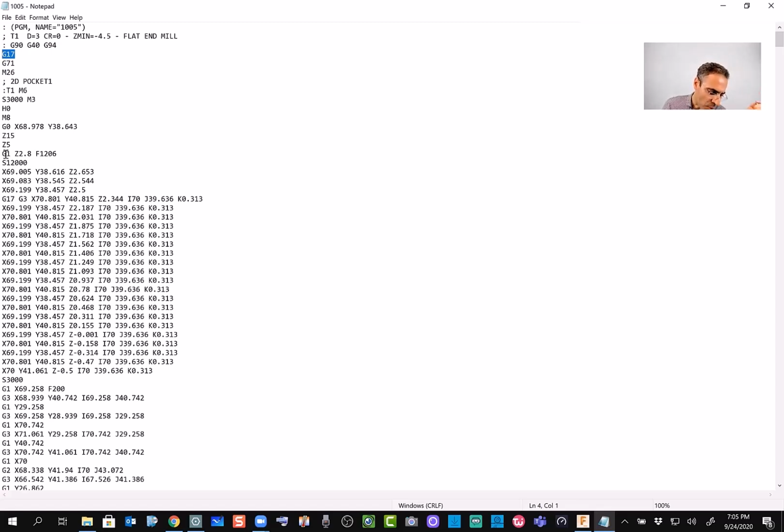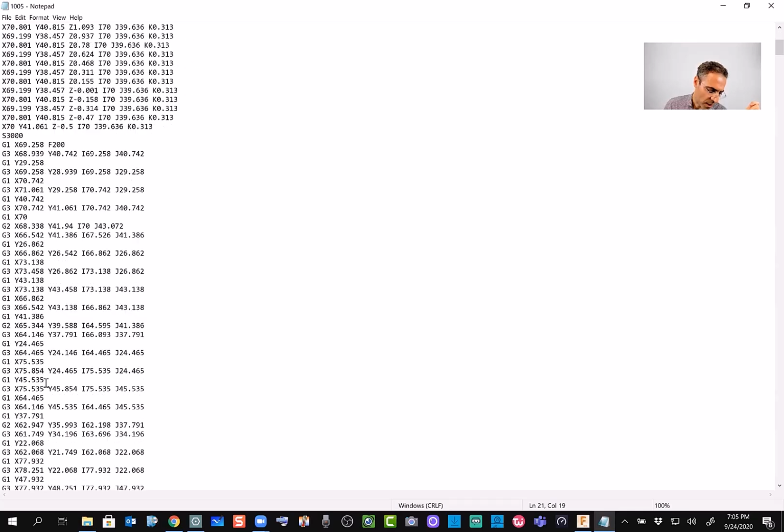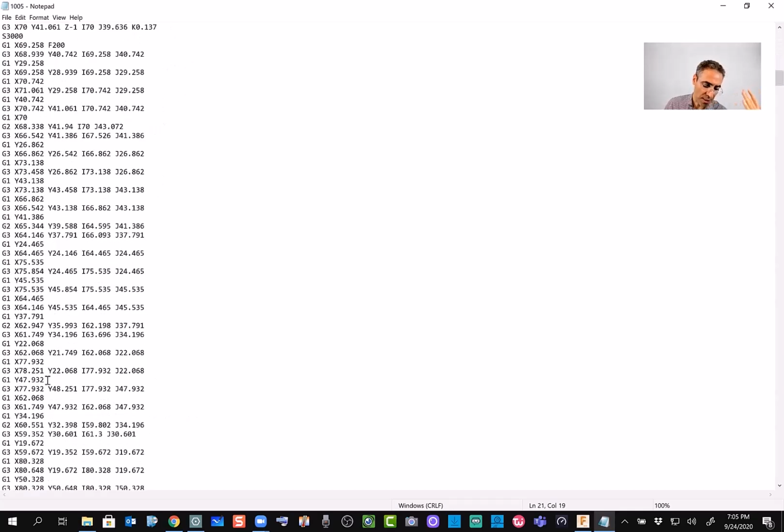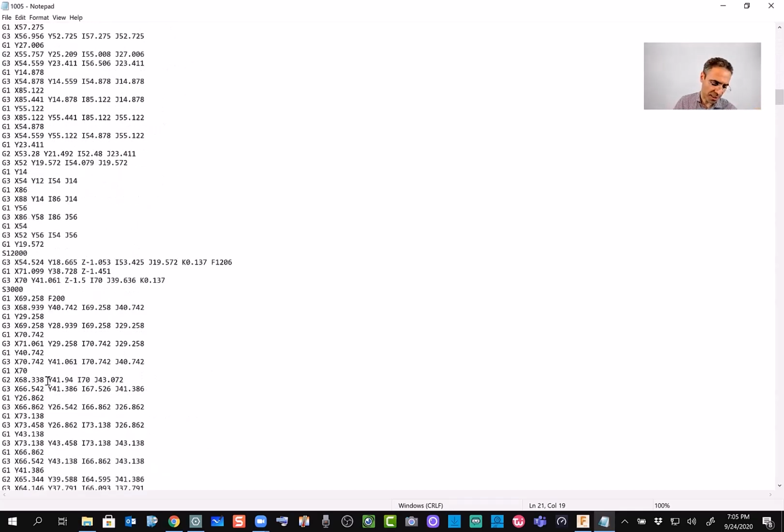And at some point, it is just X, Y, Z. It's just the coordinates. You say, my first point is this X, this Y, this Z, right? And this is the I, J, K, and they're like the orientation of the tool. And then another X, Y, Z, and so on. You see, all these things, the program has created for us.